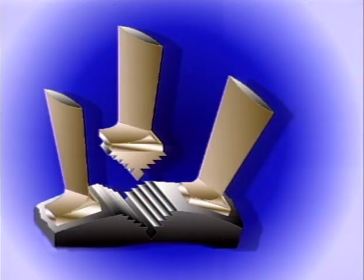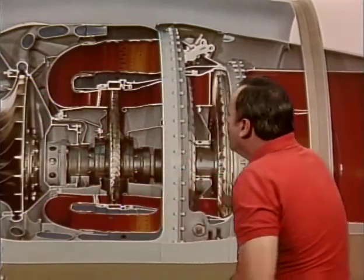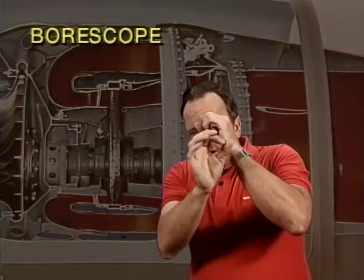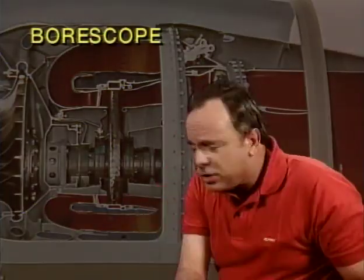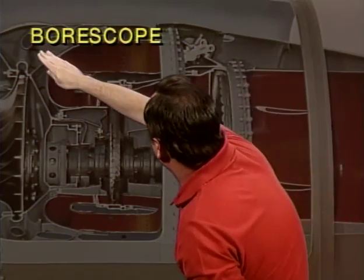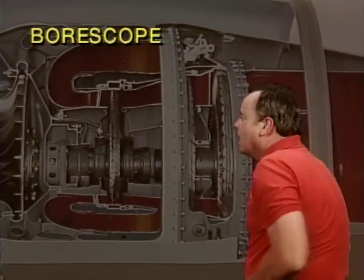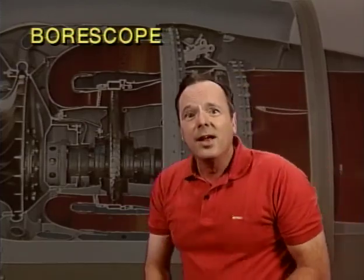Now let's take a look. Let's assume you want to look inside this engine and see how things are going inside. Well, there are plugs you can take out and stick a borescope in there, and a borescope is basically a fiber optic device that you can actually guide into the engine and look inside of it. You want to know the name of it? That's called a borescope, and you can look inside the engine. So a borescope, according to the FAA, is used to accomplish internal inspection of installed turbine engines.